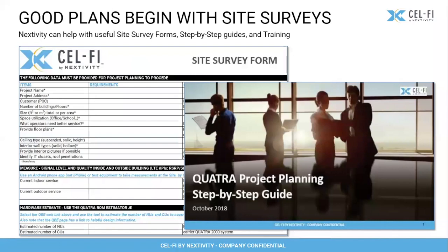Inside, because we want to know what the current serving cell is, what's dominating throughout the building. We also want to know if we have a lot of signal of poor quality, that's interference that we're actually going to have to dominate over, because that would mean more hardware. Or if it's strictly a coverage problem, maybe it's a warehouse or an underground parking structure where you have no interference and it's really just a coverage problem, then it actually takes less equipment to do that. But you have to measure in the building to find out.